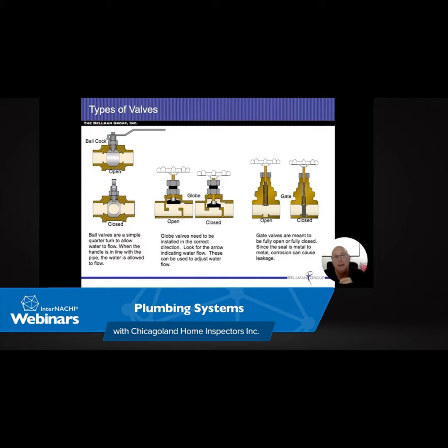Cleanouts. This is common sense, kind of, all right? The sole purpose of these cleanouts is going to be to get a rod or a jetting machine or a rodding machine in there. In case there's a clog, I could get something in there and spin it and free up that clog. And this one's roughly about 10 inches before I hit that concrete wall.